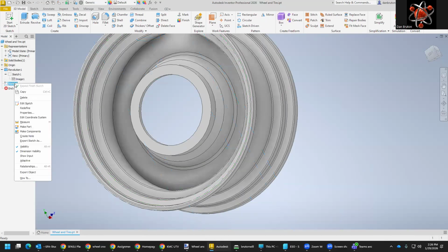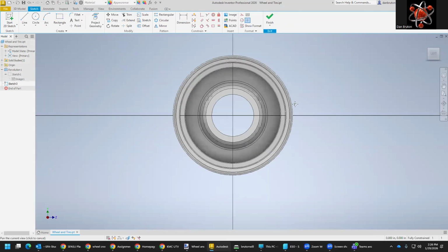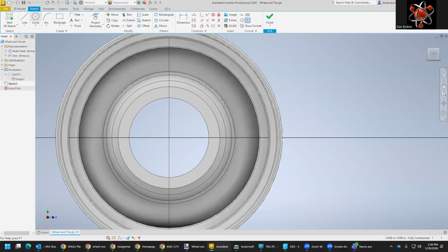All right, so back to my sketch over here, edit sketch. It goes off screen. That was the part I was trying to avoid, but that's okay. Circle click, and then remember to go 156 millimeters for this one. Make this a dotted line. And we're going to drill our holes right here. I think they're 3/8 of an inch. So let's make one of them right here and see if 3/8 makes sense. So there it is. And we need 4 of these.